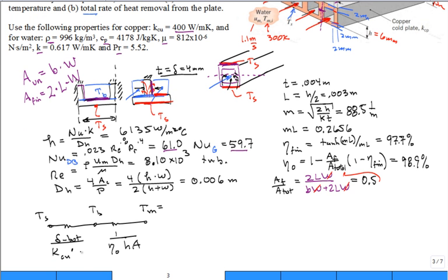So this is cap S. We'll use that symbol. These two resistances are in series, so we can sum them to get the total thermal resistance, moving from this surface at 360 to some mean fluid temperature. That is 1 over UA, the overall heat transfer coefficient times area,